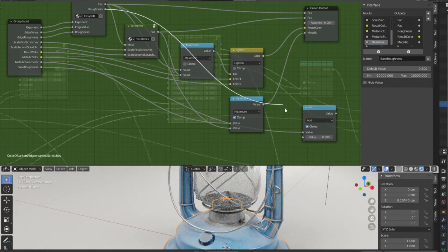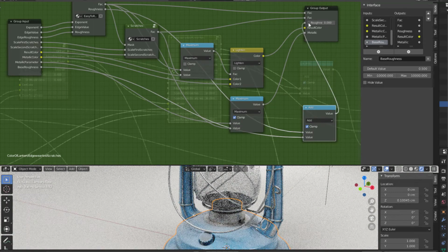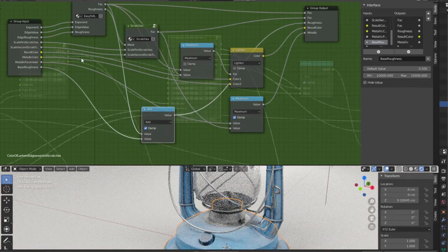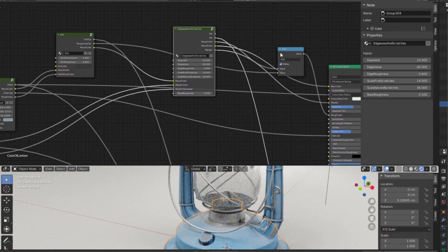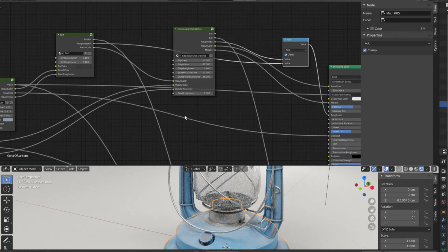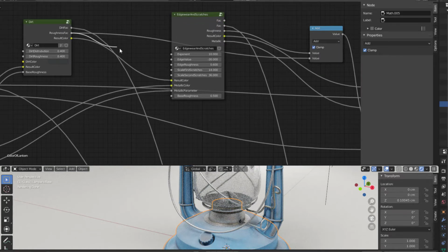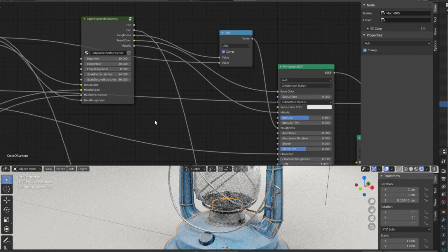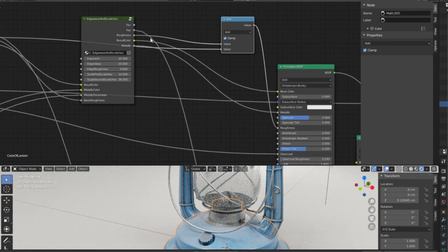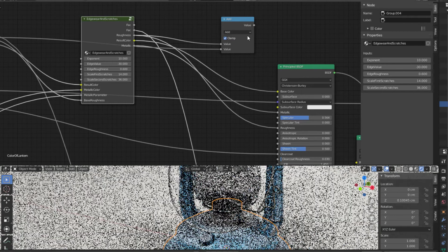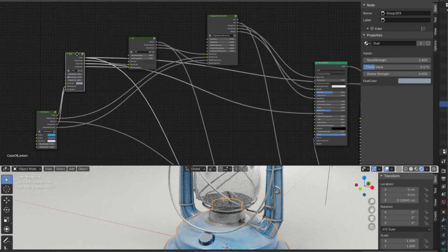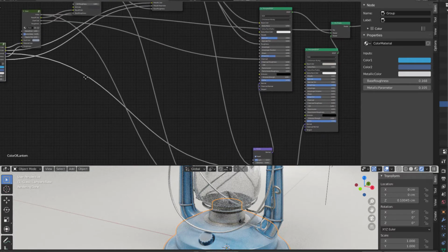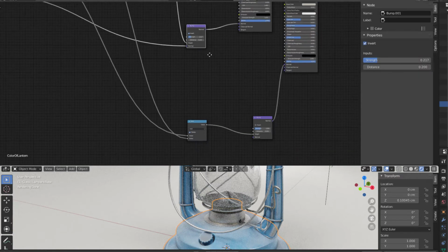So we just take that out to this and put that into that, and now we have connected all stuff in here, and we press Tab, and then we have a roughness going out, and then we have a roughness going in, so that we can drag to the base roughness, and the roughness from here we can now drag directly to roughness, and we can take away this one. So now it's getting clearer and clearer here. So now we don't have so much more to do. Let's see what we have left.